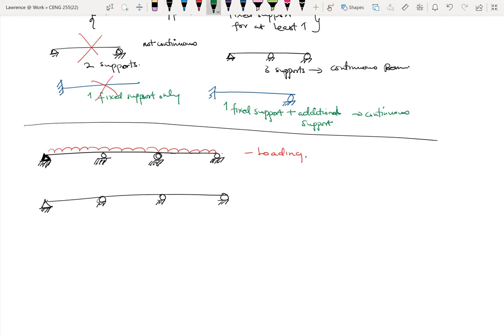All right. So this then becomes our deflected shape. So it deflects this way. So this is how the beam is going to bend when you apply this particular load onto it. The supports will not move, but the spans will begin to deflect downwards. Here we are assuming the load is downwards. If the load is upwards, then the deflected shape would also be upwards. So this is the deflected shape, or the deflection curve. Deflected shape, I think, sounds better.